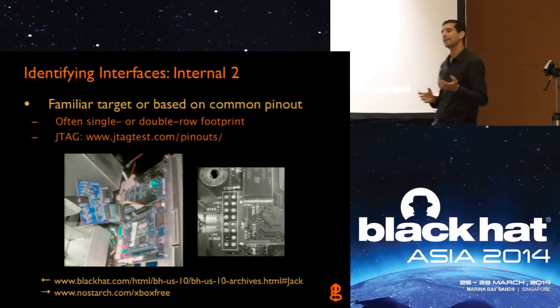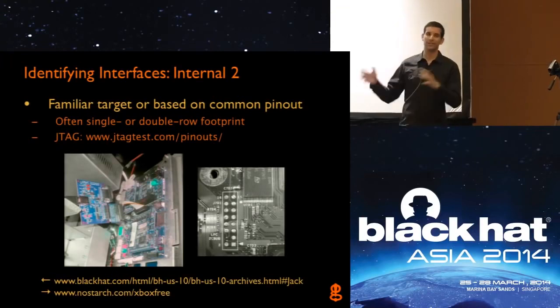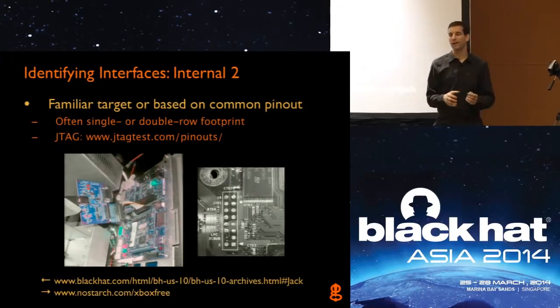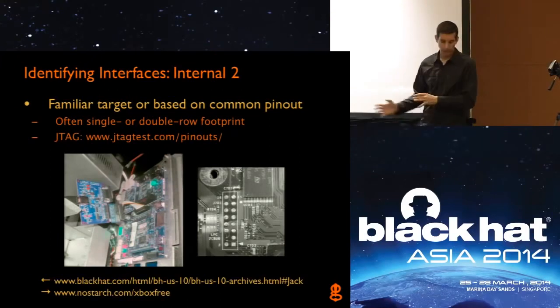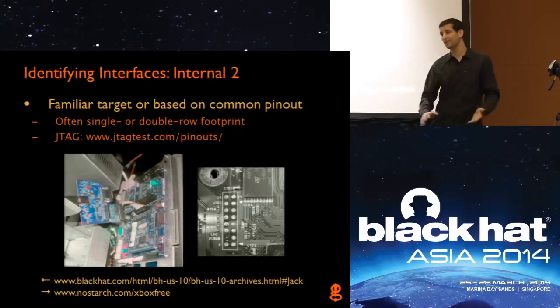It doesn't mean that the engineers are going to use those pinouts, but it makes their job easier, right? Because if they just use a standard pinout, then their standard development tools are going to work on it right away. They don't have to create some interface module to make it harder. So a lot of times we'll see just a standard interface that we can plug into with JTAG hardware, not even needing JTAGulator at all, because we already know the pinout, plug in and go to town.